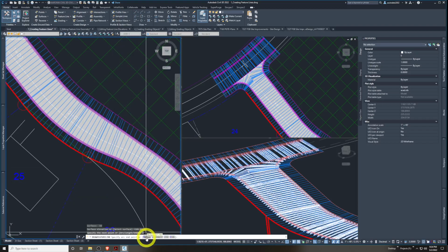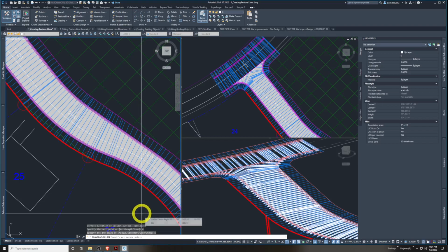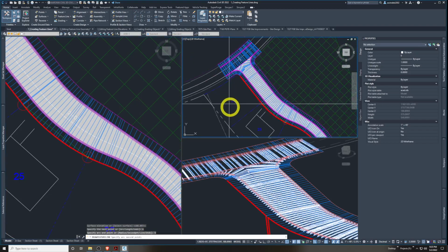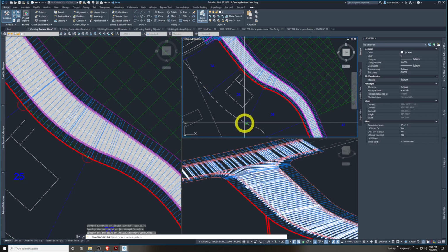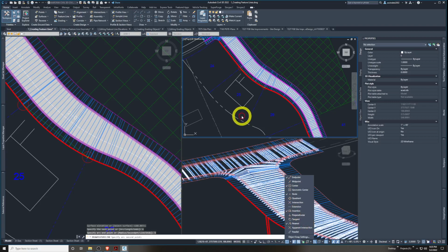We have a few different ways to make it. We can specify the radius, a second point to begin it, or give a line bearing. In this case, we're going to pick the second point option. It wants us to go to the top right viewport to do that, to pick somewhere nearest. This gets a little tricky to say somewhere nearest, which is basically hovers anywhere on a line or object, but not in a specific spot.